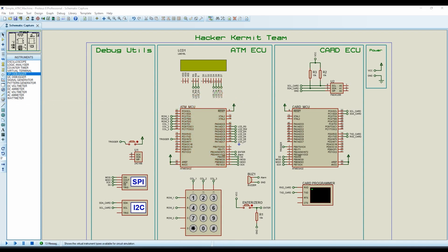For this project I was responsible for developing the DIO, SPI and LCD drivers, as well as the algorithm and flow for the application layer for the ATM ECU. Regarding testing, the DIO and LCD drivers were heavily tested in our past projects, so we just ran quick tests on them.